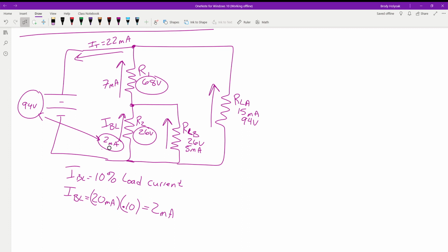No, but you could wire them together in series. You can. Some of the power supplies you guys have have the capability of spitting out 65 volts. Those are the ones that have the 2 adjustable sides plus the 5 volt in the center. You also have the other ones with 4 output terminals, and you could technically wire those together. I think it's about the same, about 60, 65 volts if you were to go the max on everything.